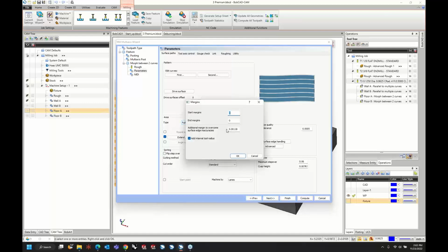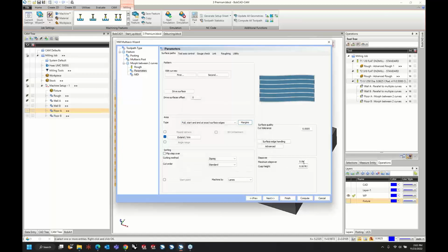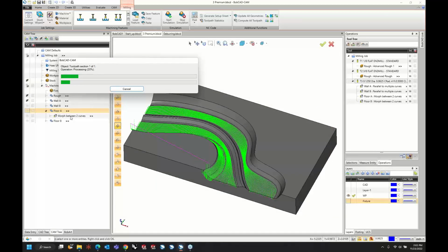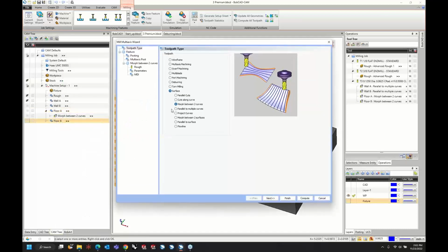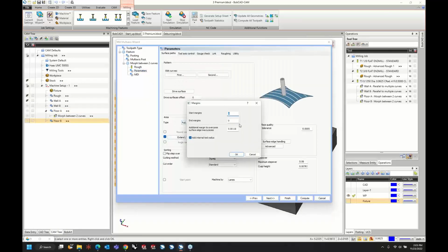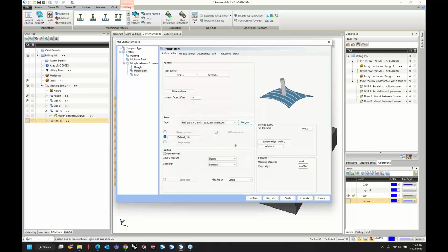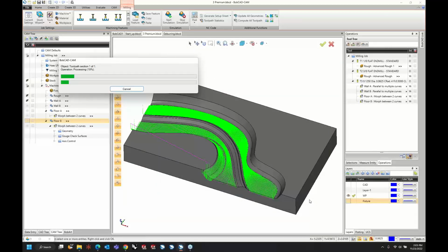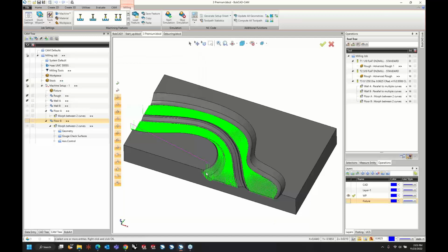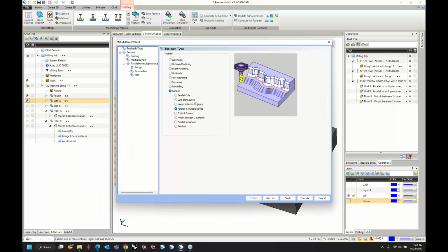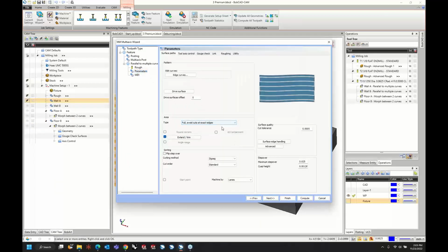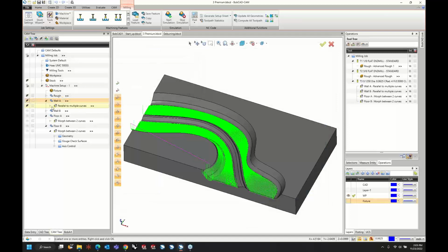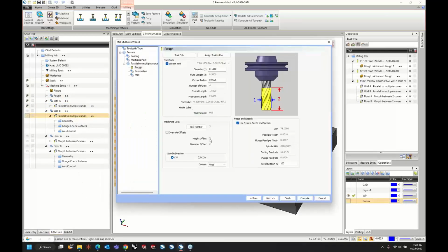I'm going to do the exact surface edges, and I'm just going to remove the internal tool radius. And we'll go down to a 25 thou step over like it is on the top. I can even change my walls now so they don't have such odd paths. So we'll get rid of the internal tool radius, change our step over, and compute. Now that means I can change my walls to avoid cuts at exact edges, because that actually gave me a pretty decent cut where it wasn't doing some extra work.